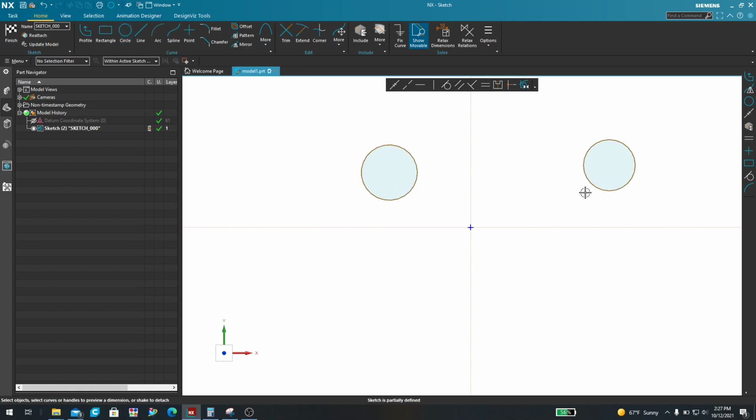Okay, one thing that you should be taking note of is that there are no auto dimensions anymore. You don't get that. Another thing is that if the sketch is brown, that means that you can move it wherever you want, which means it is not constrained. Also, if the curve is closed, it gets shaded a particular color. Okay, that's fine.